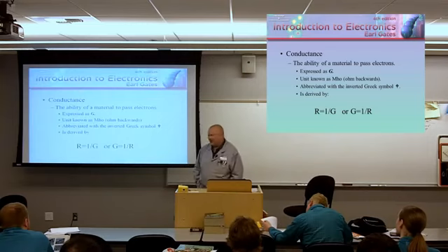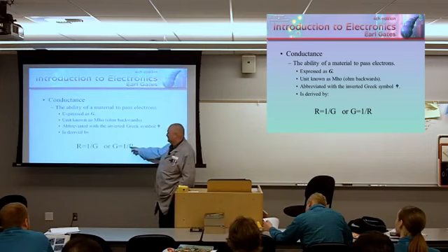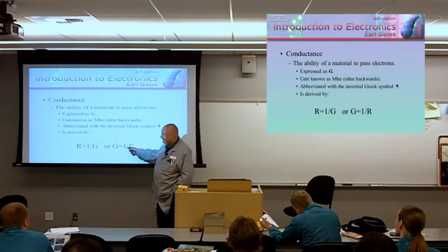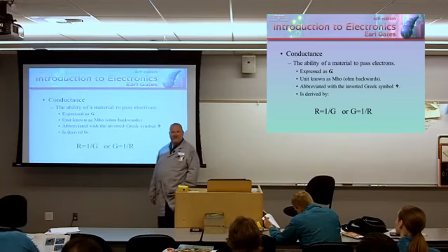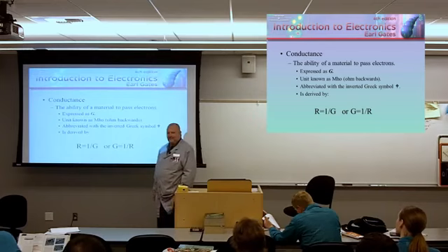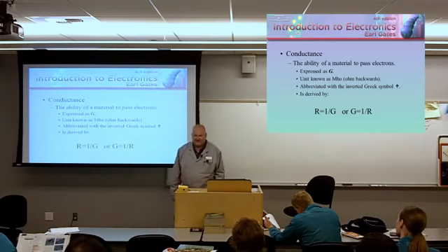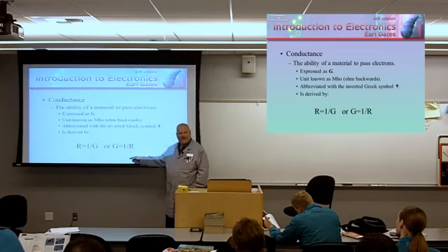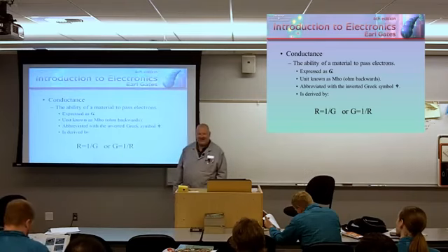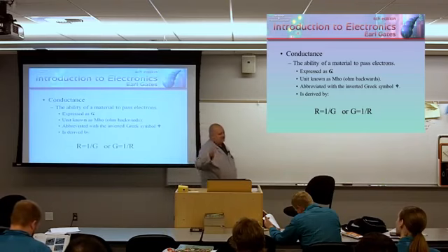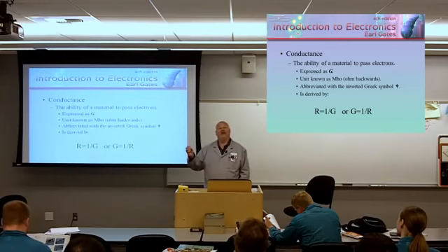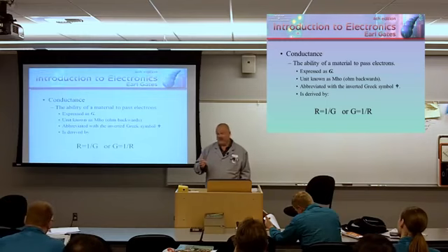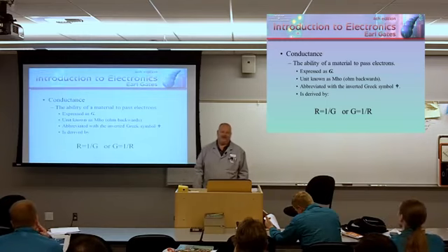Well, how do you calculate it? It's real simple. You take the reciprocal of resistance. 1 over resistance equals conductance. I guess the guy said this to his face with a straight face. So what do you say the answer is? I say the answer is 1,000 ohms. Well, 1 divided by 1,000, that's how many mhos I think it is. Since it's thousands of ohms, taking the reciprocal means that most of our answers will actually be in millimhos, or micromhos. You can't make this stuff up.